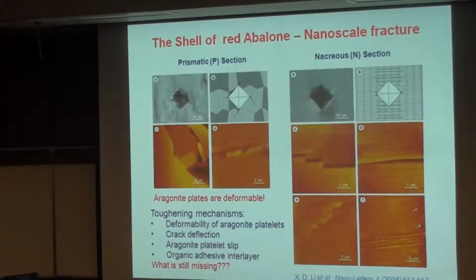And people thought previously those bricks are single crystals, and the major mechanism for strength increase and toughness enhancement is the crack deflection. So you can see from the fracture surface, and here if you make a Vickers indentation, this is crack deflection. And if you look at the crack deflection, you can see those bricks squeeze in, squeeze out. And the surface nanoasperities squeeze out. That means those surface nanoasperities serve as interlocks against neighboring bricks sliding.